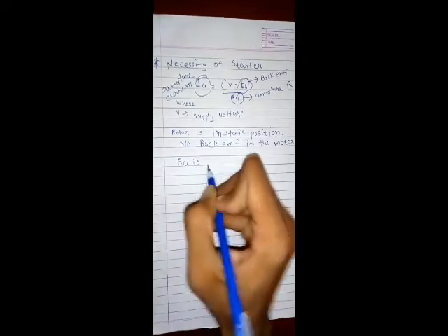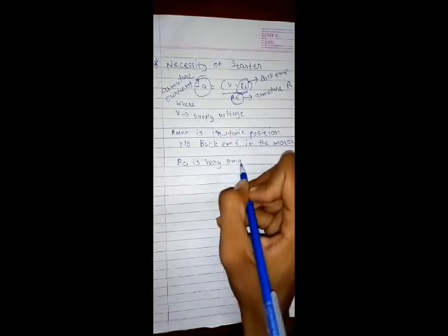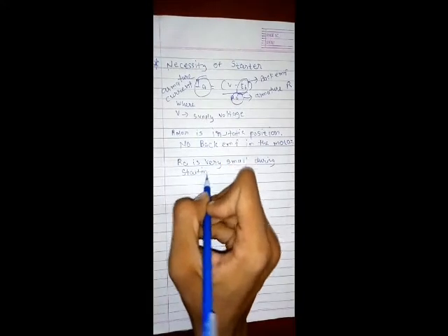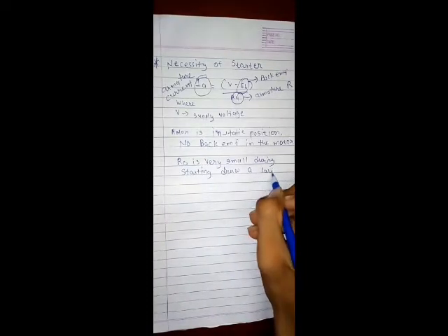If full speed voltage is applied across the stationary armature, means at starting if you give the full supply voltage to the armature, it will damage the rotor, because it will draw a very large current since the armature resistance is very small. So during the starting period the motor draws a large amount of current.